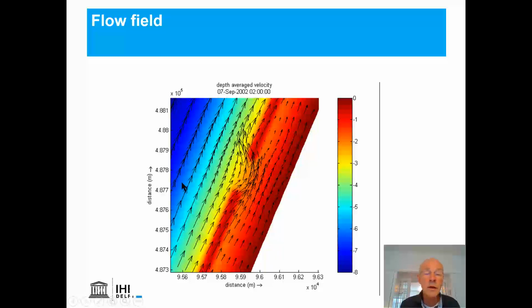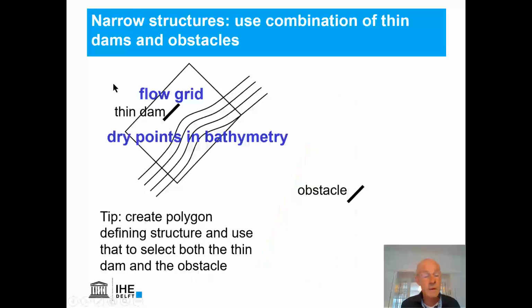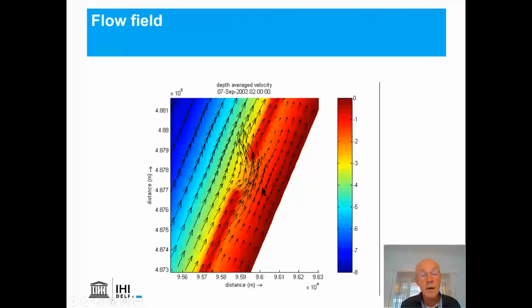So after a few iterations, you end up with this kind of pattern, with a longshore current that is here. So these are pretty oblique waves, and there's a strong wave-driven current on the bar, but then it gets a strong offshore component here, which is extremely dangerous for swimmers.